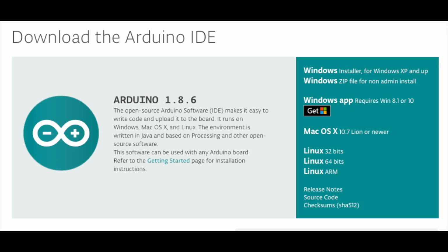They're already developed for 8-bit, whereas they either may not have been ported yet to 32-bit, or they may never be ported, or may not be possible to be ported. Also, the IDEs you were used to working in, like the Arduino IDE, are all optimized for, like I said, the integer twiddling and optimizing for 8-bit bandwidth. So we have to move into more unfamiliar territory, and a lot of people have moved on to PlatformIO and VS Code and those types of things. And most importantly, the firmware is very mature on the 8-bit stuff, and it's still fairly new-ish on 32-bit.